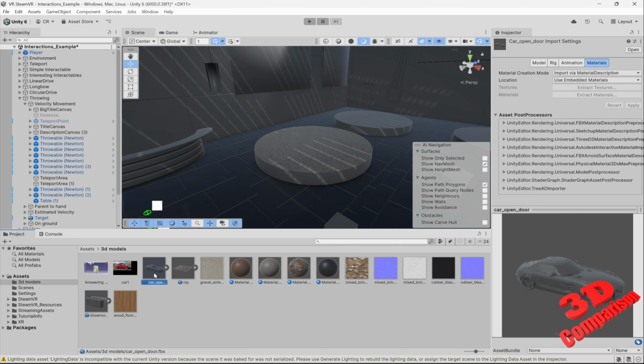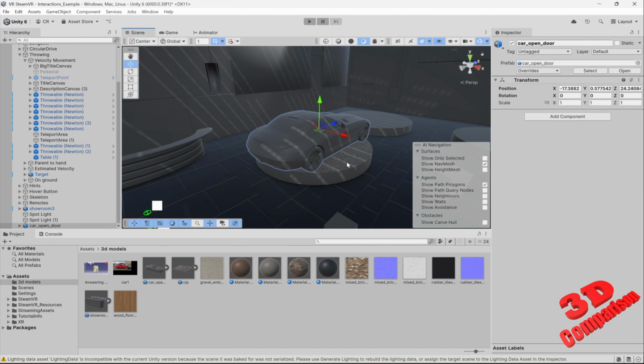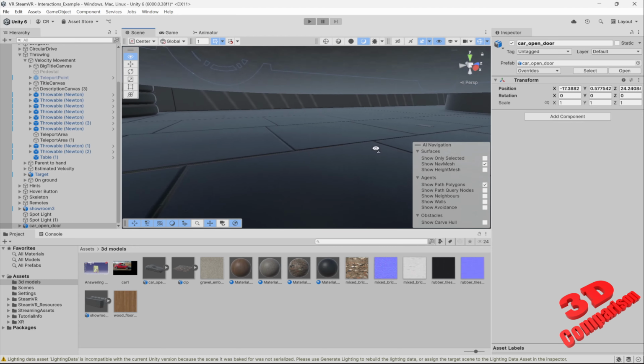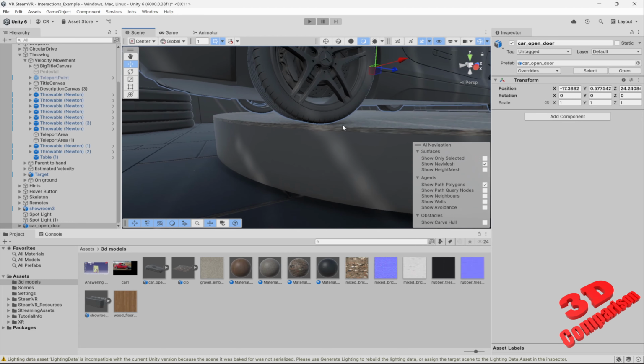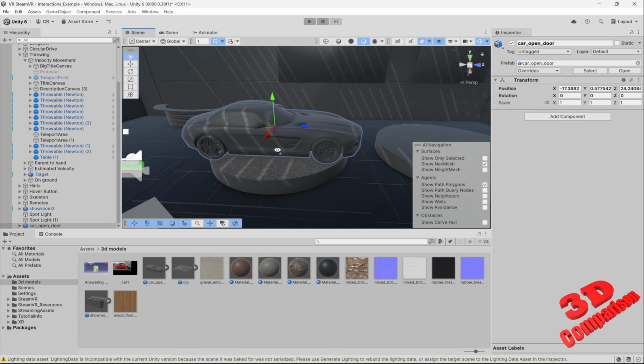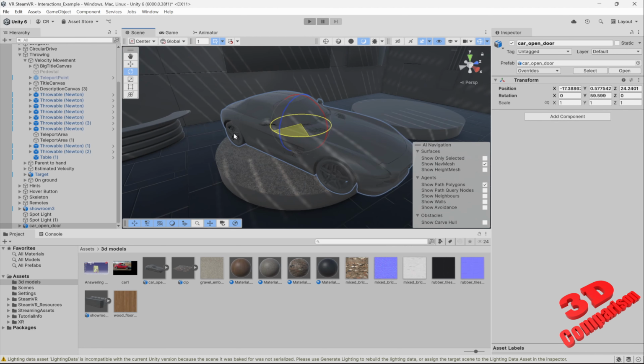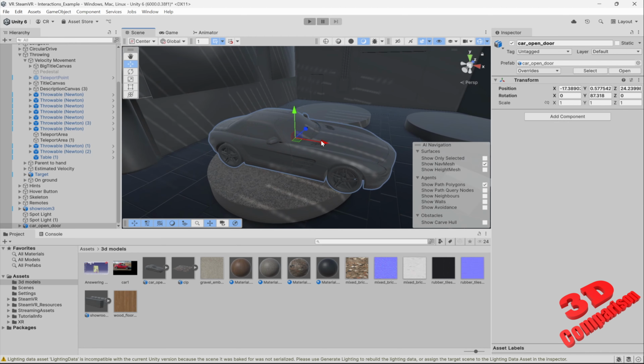I can drag and drop it within the scene. As you can see over here, I cannot position it over here because I didn't add collisions, but over here, since I added collisions for this cylinder, I can directly fit it over here. You can always move it afterwards, but if you add those collisions, it will automatically identify that sitting position. So this will be the model of the car. We can also decide the rotation. I will leave it, let's say, maybe somewhere like this.